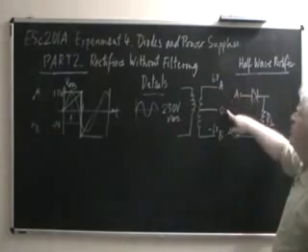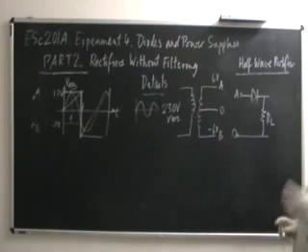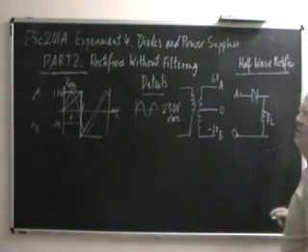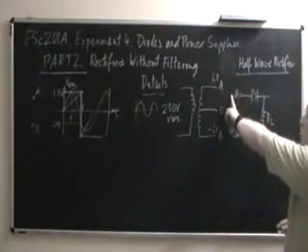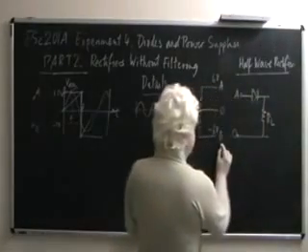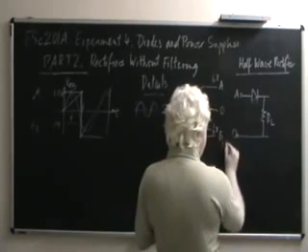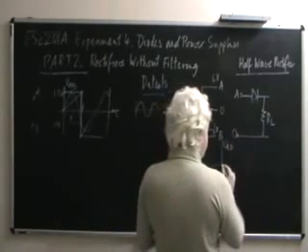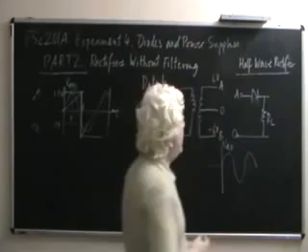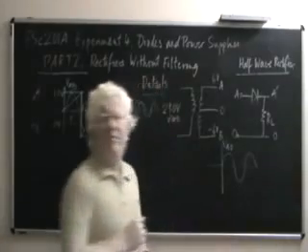What we do here is observe what happens in different parts of the cycle. When A goes positive with respect to O by any positive amount, this diode conducts. We can use here the ideal diode model, and so what will happen here across RL is that the voltage between OA is transferred to RL. So, while the actual voltage VAO will be this, what will appear between VA dash and O will be the following.